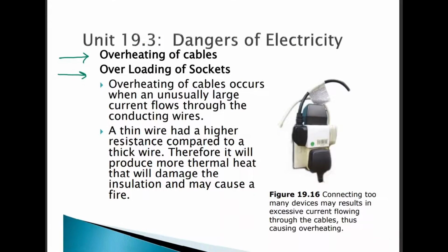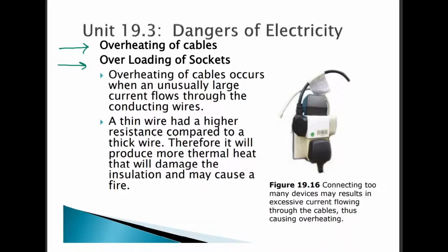So it's a bad idea to overload the sockets, which will overload the cable that actually brings current to the socket. If you demand a lot of appliances or a lot of current from the same socket, that is a bad condition. That's a hazardous condition. We should not be using appliances in such a way.